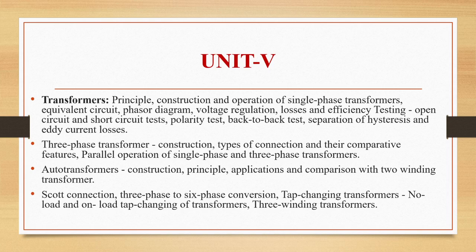What is an ideal transformer? An ideal transformer is one which has no winding resistance, no leakage flux and no iron losses in the core. So input should be equal to output in the case of an ideal transformer. But in a practical transformer, this will not happen. And we have seen each and every case, that is ideal transformer on no load, practical transformer on no load, ideal transformer on load, practical transformer on load, and phasor diagrams for each of them we have seen.